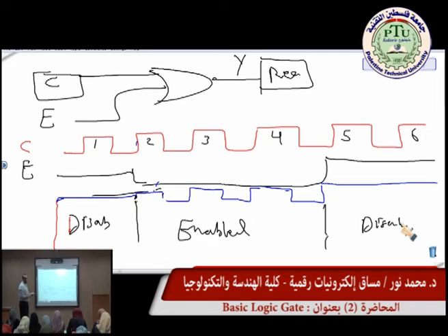So this means we can use it as a combination, right? Use both AND and OR gates to again do a certain logic function. When enable is zero, shouldn't the control be not working, meaning it must always be zero? It depends. Here it is disabled from the perspective of this logic gate, but for the control, yes, you are sending high voltage. We can put an inverter. From a controller perspective you are enabling, but from an application perspective for this circuit you are disabling the signal.